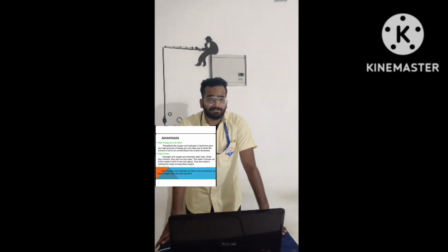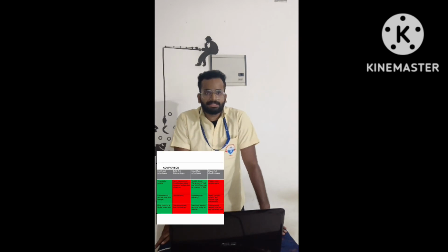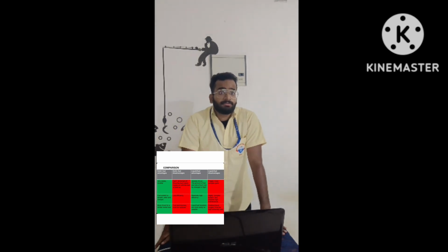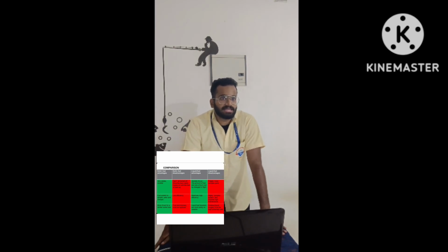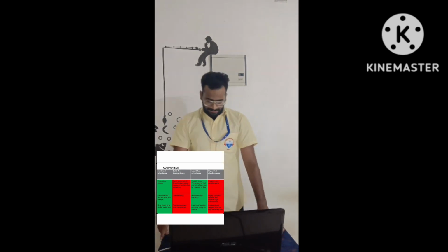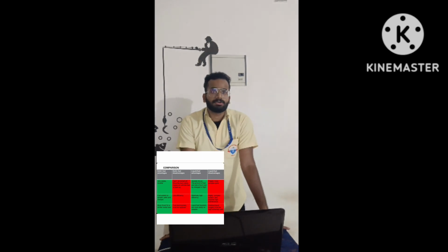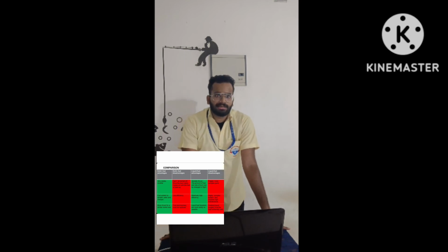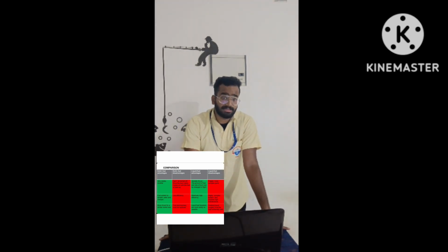On this page, we will see the comparison of the cryogenic engine. Solid fuel advantages: very stable, durable, the fuel system is simple, safer, and cheaper, and more thrust for similar rocket size. Next comparison is about solid fuel disadvantages. It can't be turned off once the burn starts; it goes on until the fuel is used up. Low efficiency. Fuel decomposes, must be replaced.